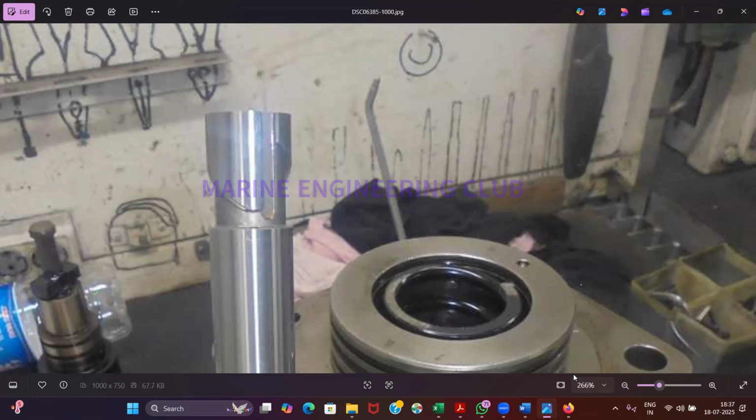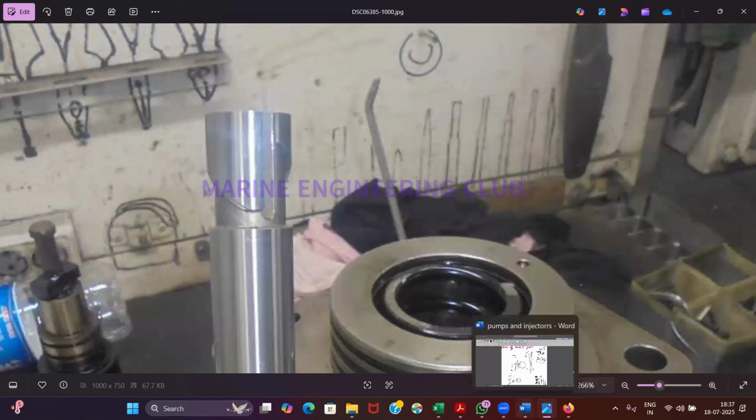Even the superintendent was there on board, standing there itself. We started it, and then the superintendent told us to stop, and we could not stop it. Even when we pulled the complete lever back, it was not getting stopped. Then we had to close inlet and outlet. Again, it was not getting stopped because the line oil would completely be consumed. After completely consuming the line oil, then the engine stopped.